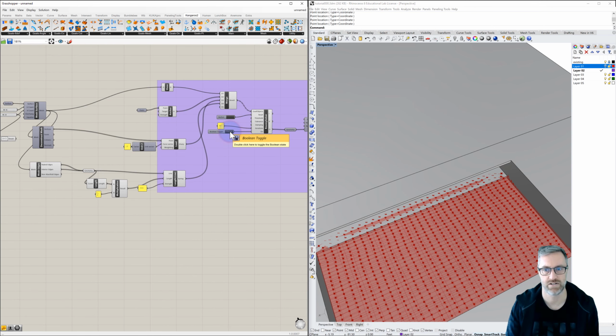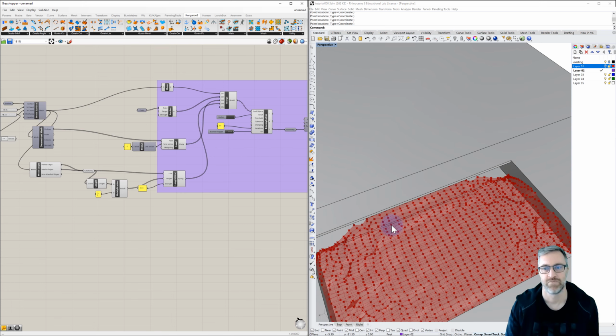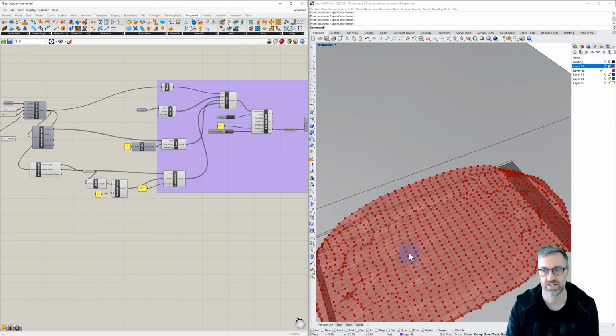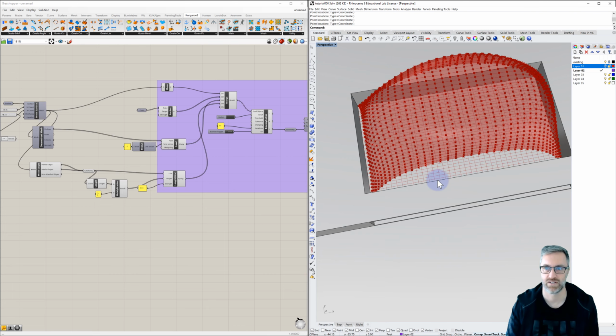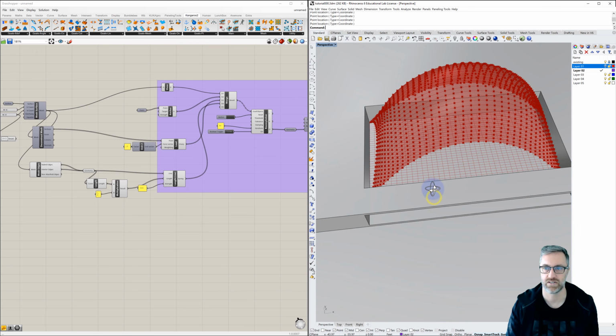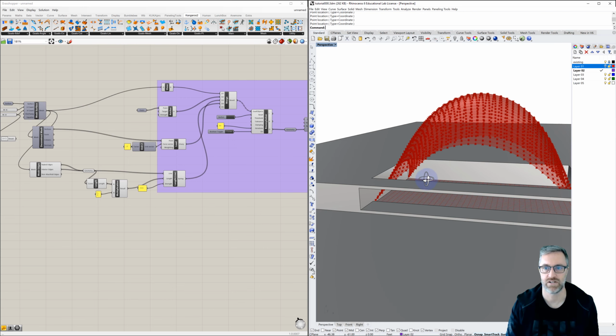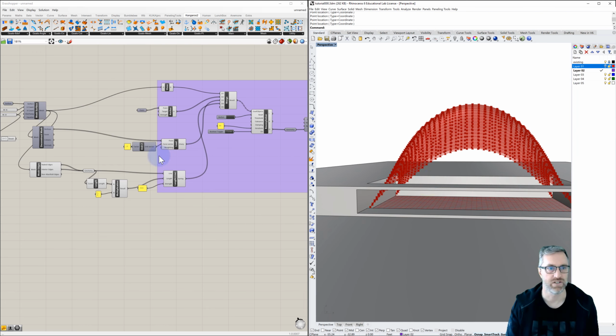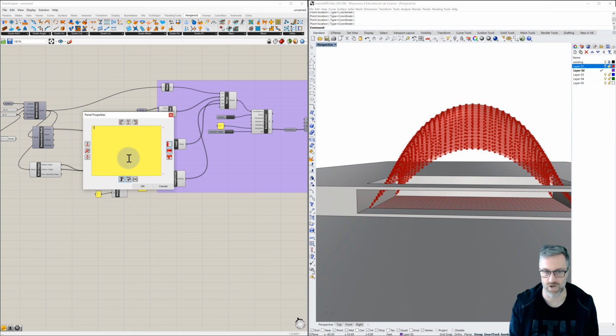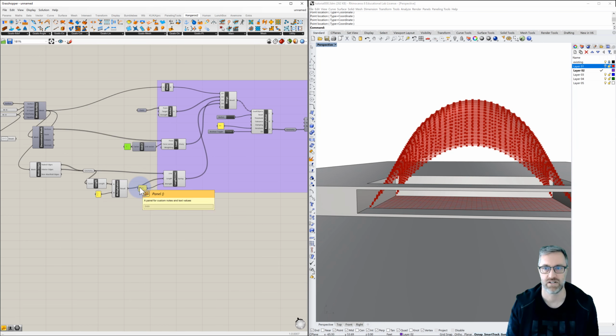Let's turn on our solver. We see it working. So what we have is a force applied in the positive z direction, which is a 0.5 force. This is really tall, but if we change the force to be 1, we'll make it even taller. We'll stretch more of those elements. We saw more stretch occurring in the lower portions because of all of the load, and again, the kind of tributary force applied to those.